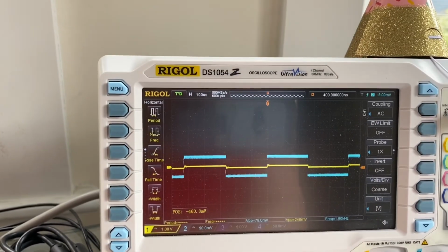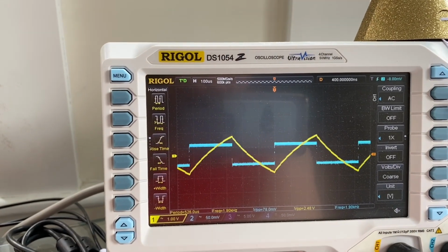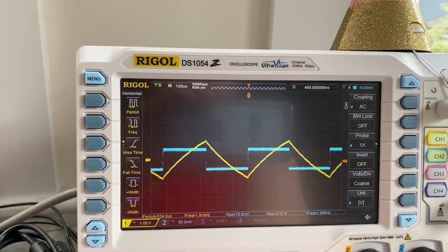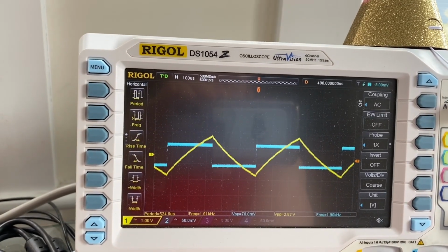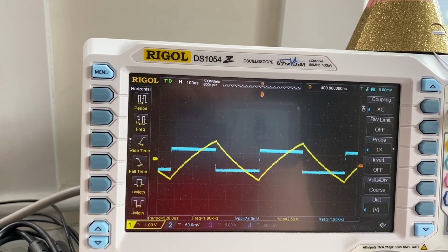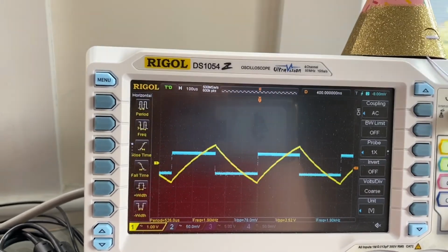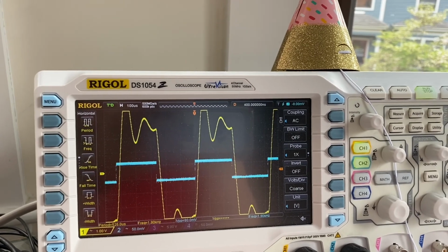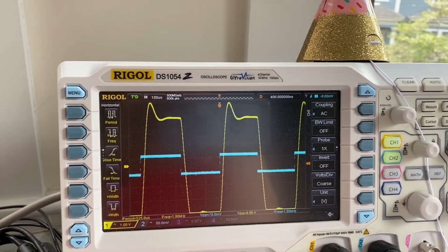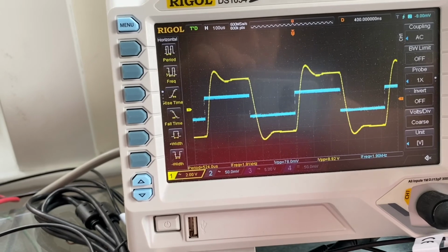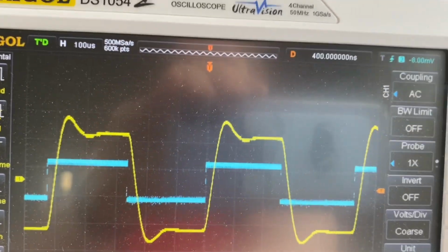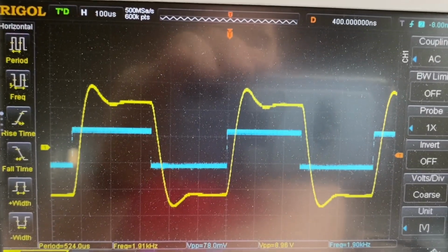And if we go to the extreme, let's get our gain of 100 up. This is a gain of 100 with that capacitor that was sized for the gain of 2. We see that that capacitor is way too big, and even though it's working, it's damping our oscillations too much. And here's a smaller capacitor I've sized properly. And we can see, look at that, it is damping just enough, but not too much where we're rolling off our final value.